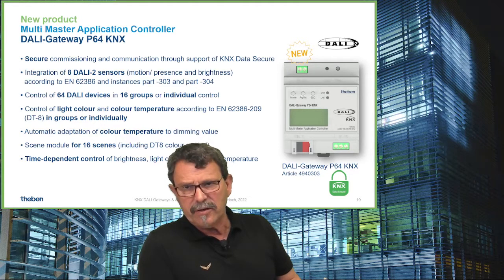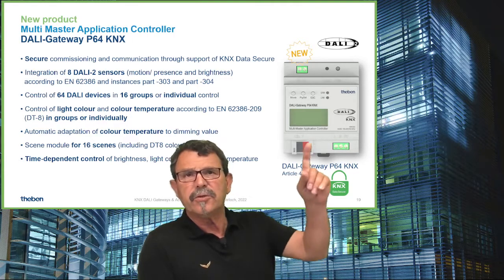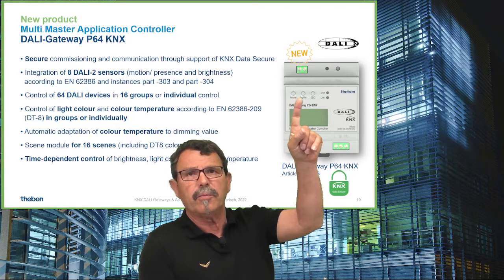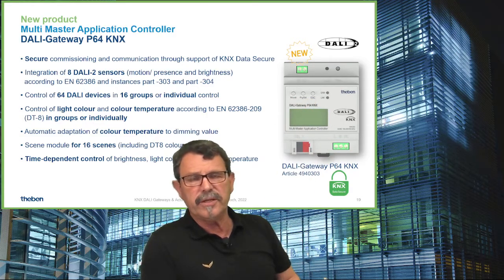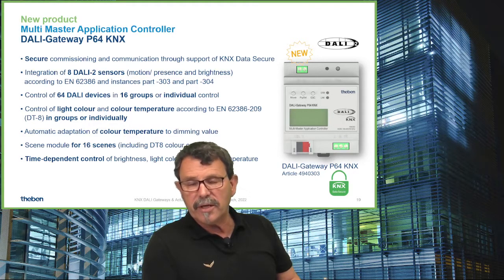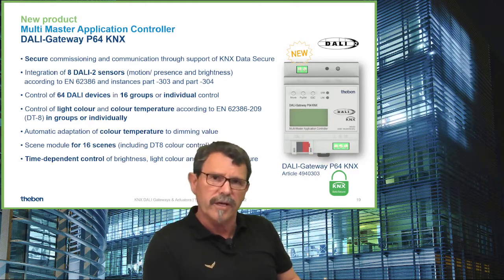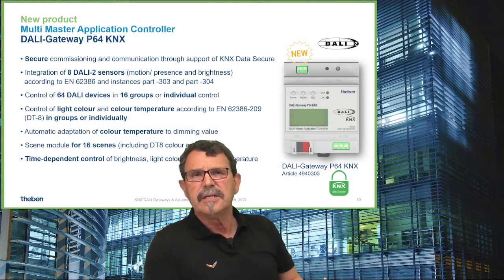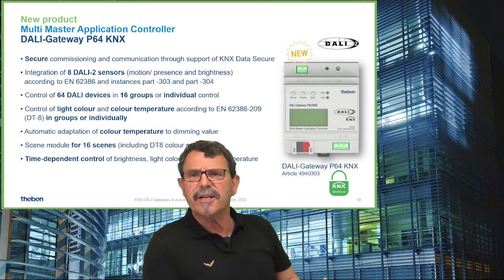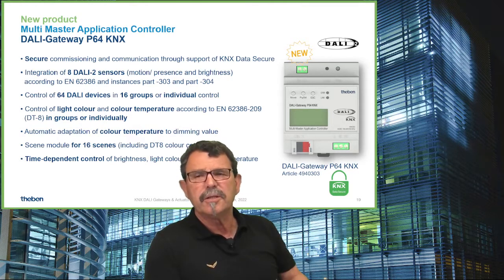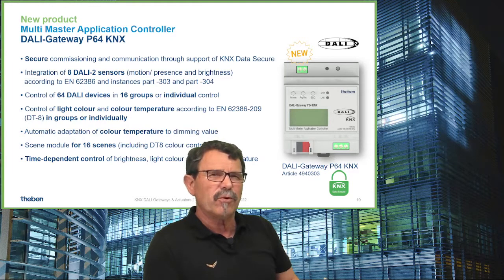The programming options we have for this DALI gateway are in total 3 of them. First of all, you can operate manually. That means you can do the customization on these keypads directly on the appliance. You get feedback from this display. It's really nice, but a little bit sophisticated when you intend to control, manage, and set reasonable applications for 64 lights.